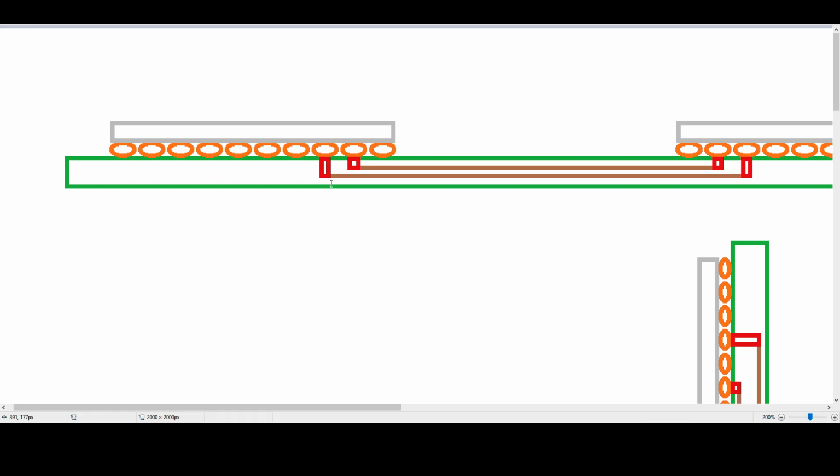So we have challenges here that we need to overcome to maintain our signal integrity, because we're already transferring through different mediums. We have to transfer through these solder balls on the bottom of the package. We have to go through the via, then we have to go through the conductor. The conductor might not be straight either. There might be interference from adjacent conductors. We might have to put a ground fill above.